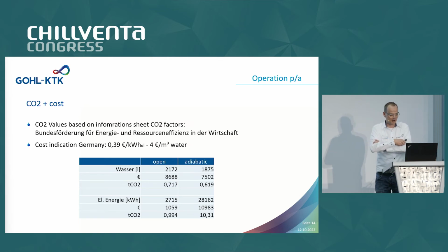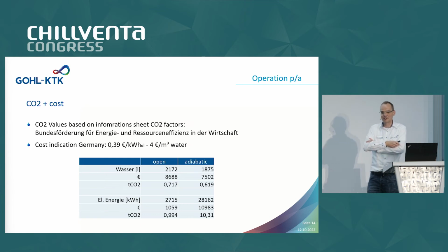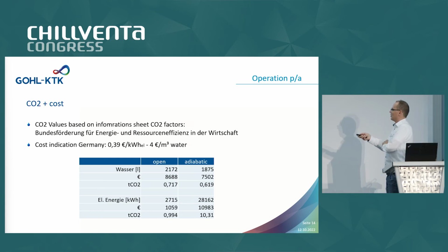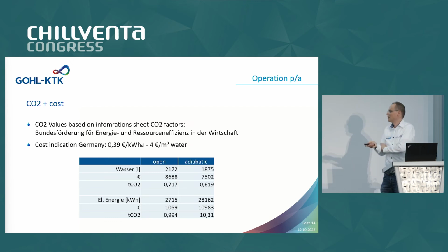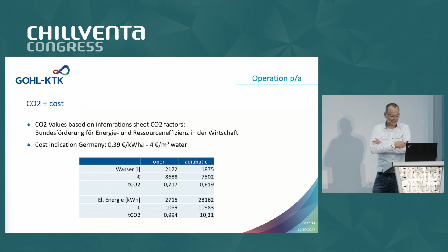So the costs for water of the open cooling tower are similar to the consumption of the water. And you see here the assumption for the water CO2 footprint. They are also in the same dimension. If we go to the electric capacity of the adiabatic cooler and the newly designed open cooling tower, we see here we have the factor 10, which we found before in the view of only the fan as well.